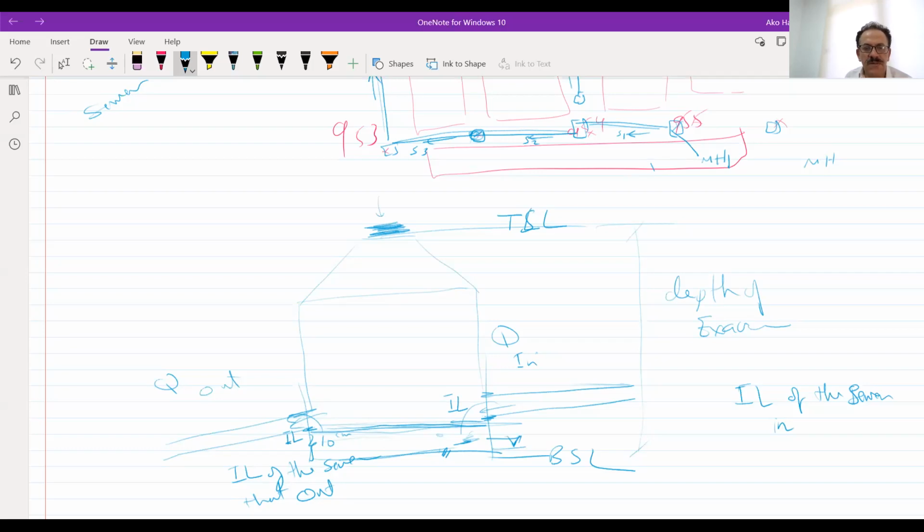And then this manhole cover can be used. For example, we need to clean these kinds of manholes every 3 to 6 months and get out all of the collected solid materials and keep the sewers clean. And there will be a ladder to help the people come down and clean these manholes. Now, as an engineer, we have to know these levels and the diameters of the in and out.